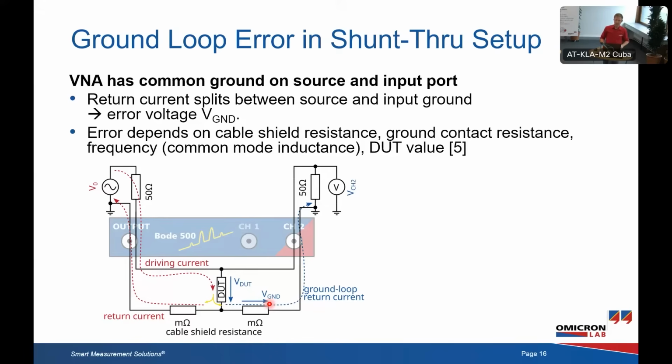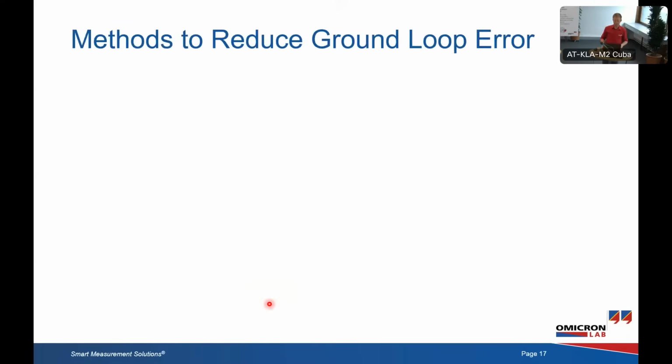And also the value of the device under test plays a major role, because the lower the impedance of the device under test, or the lower the impedance you want to measure, the more this becomes a problem. And the lower the frequency also.